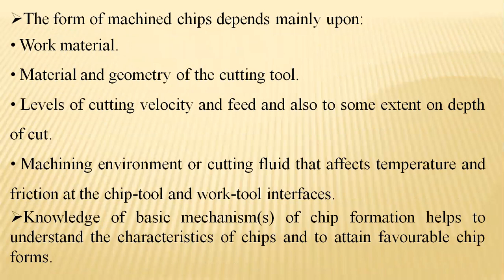Basically, the form of machined chips depends directly on the work material, the geometrical conditions of the cutting tool, the levels of cutting velocity, and the feed rates being processed in the working scenario.